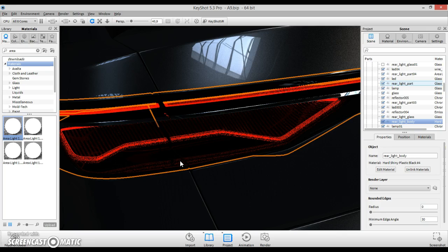So that's the thing to keep in mind. If you want to transfer light from one point to another, you have to use roughness. If you're going to use transparency, it's just going to be transparent lines. You're not going to see it in a dark environment, and basically your whole render and your whole purpose of using these kind of bars is just pointless. I don't see the point of it, and neither would anybody else if they want to achieve maximum quality and realism as well.